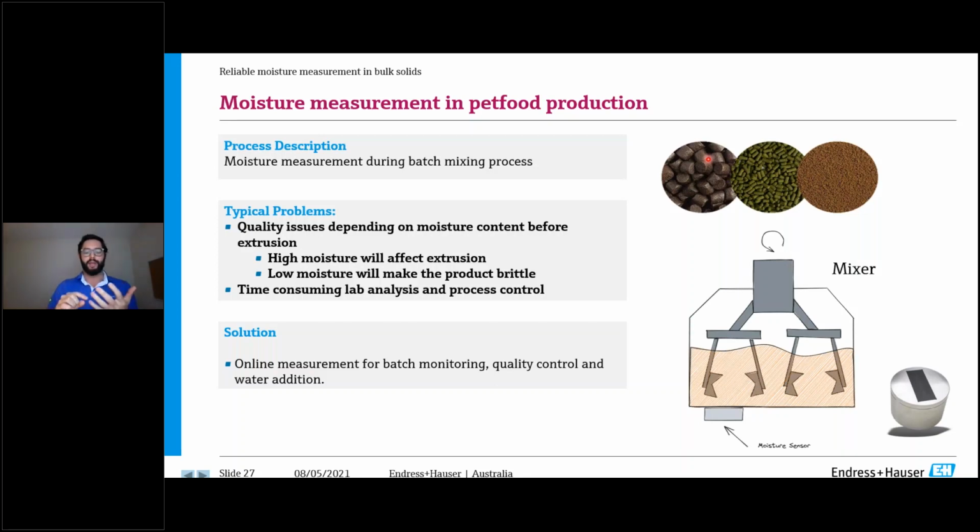This is something where you can improve your process, especially with real-time analysis. This is often a very reactive process and often relies on recipes. So if you have a recipe and the characteristics of the raw material change, this will influence the result later on. But if you have an online moisture sensor, you can create an automation. You can really improve and boost your productivity with a very simple solution, okay?